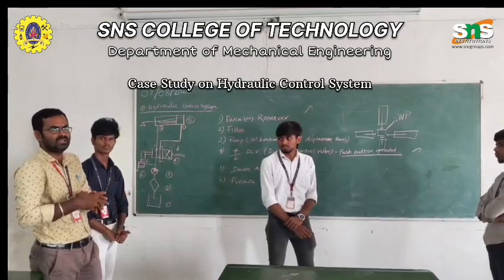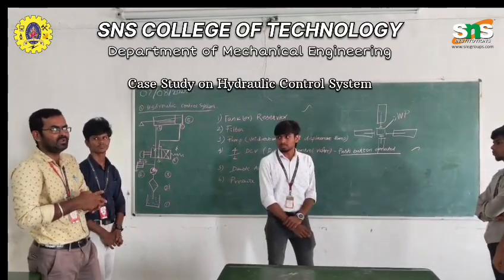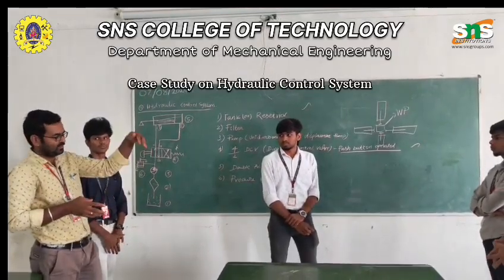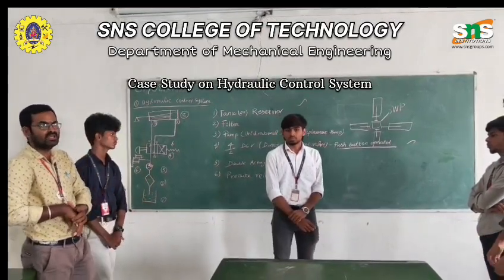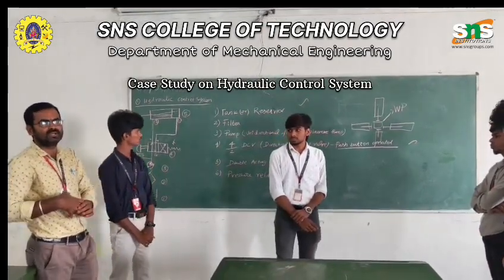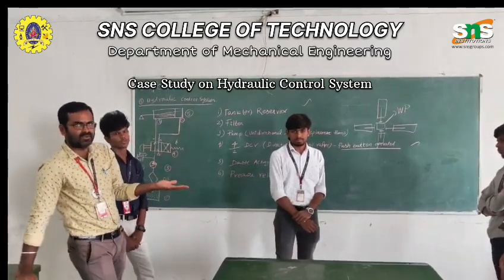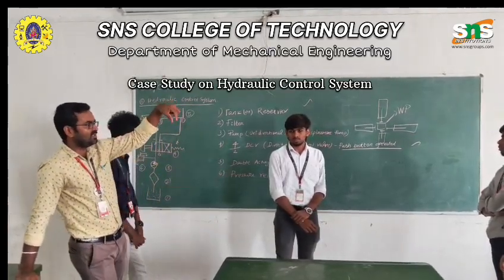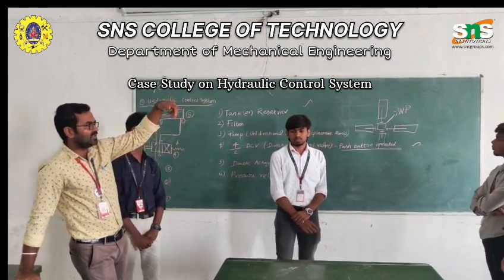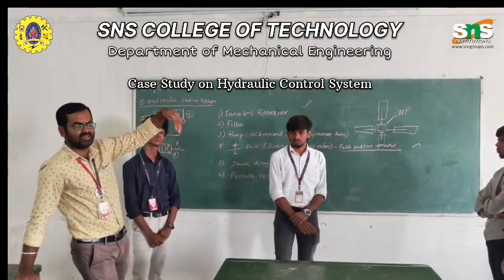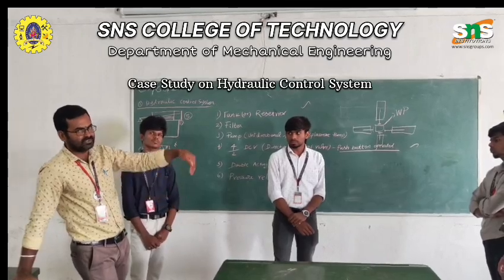In the same way, we can use a tool holding device as well, and we have to move the tool from the upward to the downward direction. For example, in a drilling application, we can fix the workpiece on the table as well as hold the tool. We can use the double acting cylinder for the actuation of the tool from upward to downward.